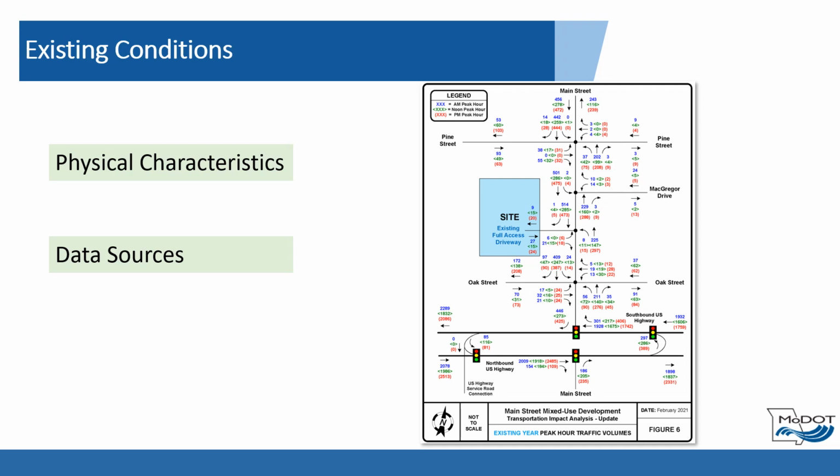These sources may include, but are not limited to, turning movement counts, average daily traffic, traffic forecast, existing signal timings, and crash data. This section is also expected to include a description of the type and age of all data used for the analysis. The traffic volumes subsection details existing traffic volumes. This typically includes intersection turning movements for the AM and PM peak hours.